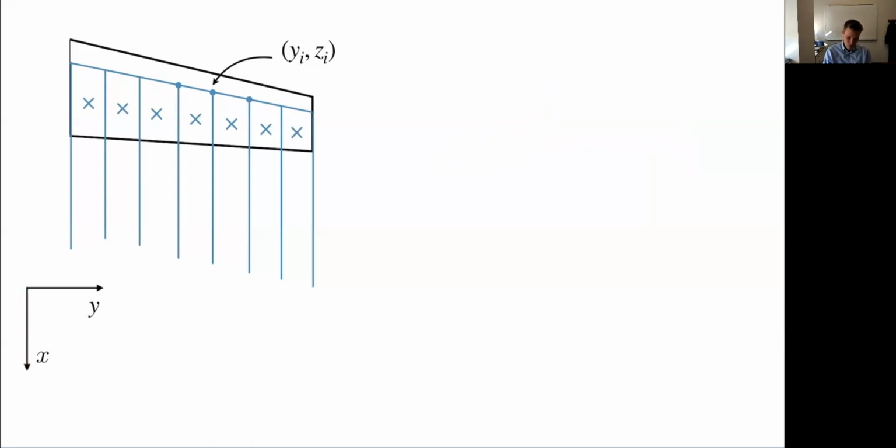And so we're going to define a few things. We're going to define the location of these nodes. Notice once I define these nodal coordinates, that completely defines all of these horseshoe vortices, because they're just going to travel straight downstream in the X direction from there, and they'll just be connected straight between these nodes as shown. So I've got Y_i and Z_i, noting both the Y and Z. Z would be up, so if I have winglets, I'd have a Z component, or if I have dihedral.